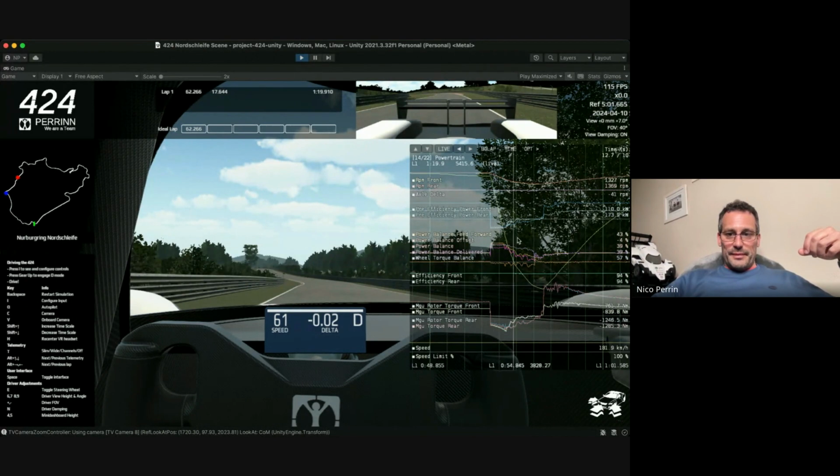We had this -4% that you saw, the second channel, called the offset. There's an active system on the car where, when we detect that the front or the rear is locking relative to the other axle, we automatically adjust the power balance to try and reduce the amount of locking.